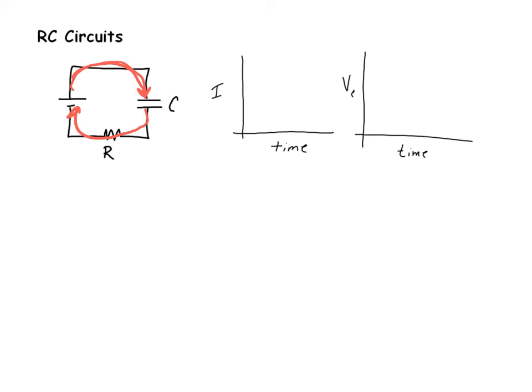Now notice that the capacitor looks like there's a gap there, and capacitors actually behave as though they're an open circuit, at least once they're charged. As they're getting charged, it appears that current flows, but once they reach full charge, then the current will stop. That's why we said it's kind of instantaneous. Now, if I put a resistor in there, that'll take an amount of time.